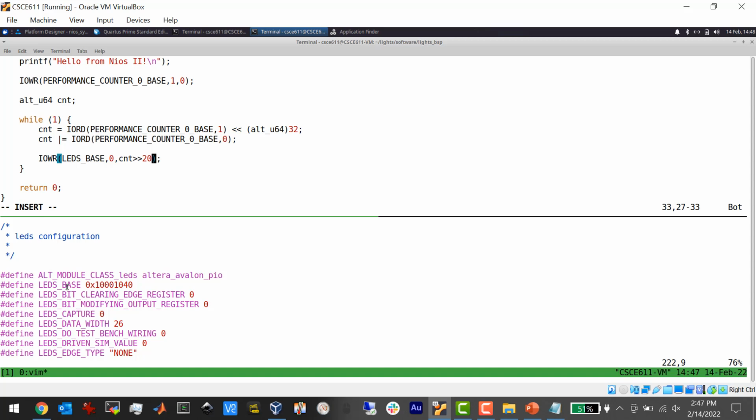And so it'll tick up once every 20 milliseconds, 50 times per second, right? Maybe I should go a little more aggressive with that. I'll go 22, 2 to the 22nd power, that's 4 million. So that would be incrementing 5 times per second or so, right?